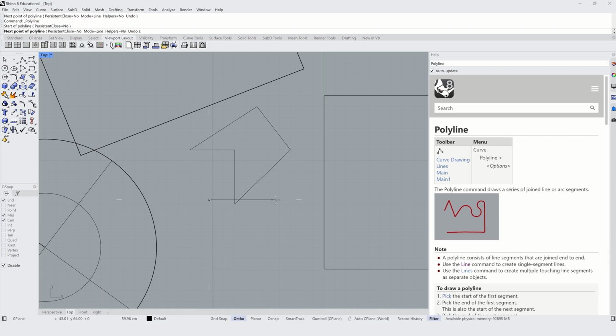orientation into one of the 4 orthogonal directions. And you have these little white hatch marks that indicate where those orthogonal directions are. Again, this is a setting that I would normally leave off because there is a keyboard shortcut to activate this ortho mode. If you hold Shift, you can see that this crosshair, the white hatch marks, come back, and my